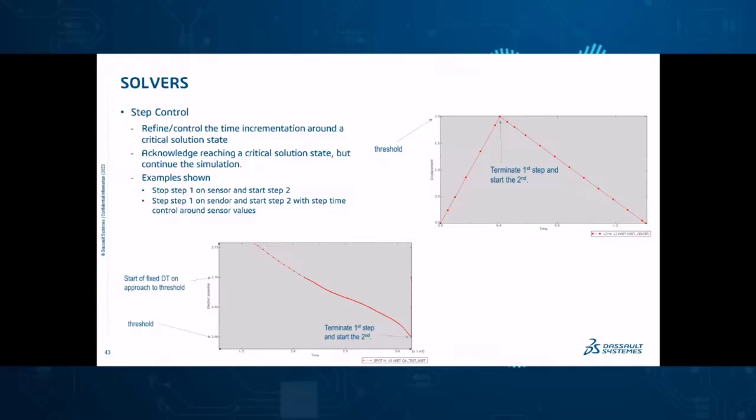And there's various options within the keyword. So you can refine the time step between two sensor values to really concentrate output. You can end the step, you can continue the step, and also you have the option to end the analysis upon the sensor value being reached.